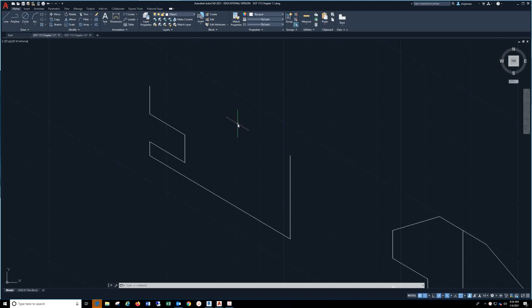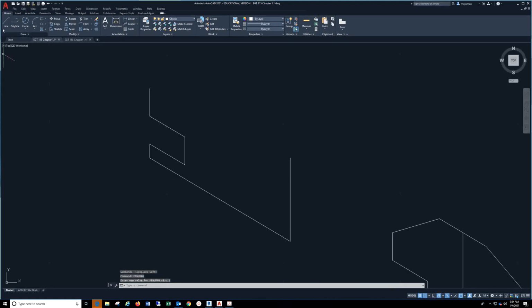You can change the plane by just hitting F5. You can see that moving around there. Right now I'm going to be here. And the dimensions are in inches, so if you don't have the screen up top there, type in menu bar, all one word, enter, and change that 0 to a 1 and hit enter again.